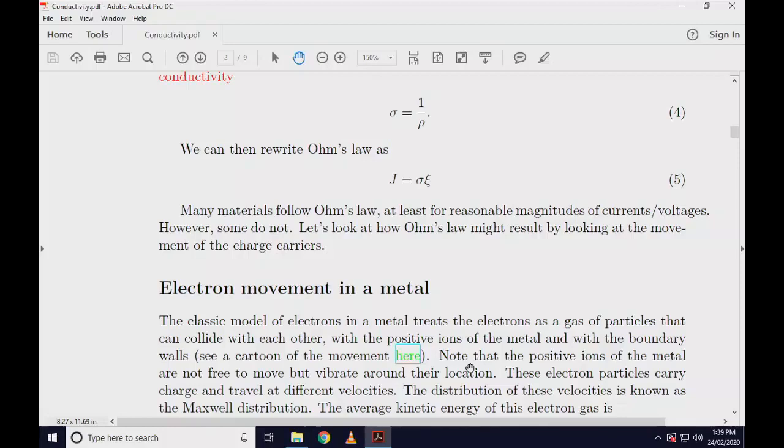But on average, that voltage is zero. Yeah? So on average it's zero. So this fact that there is a voltage, and you can measure it, if you get a chance, you get a resistor and put an oscilloscope probe across it, you will see these fine lines moving around zero. And that's the noise, what we call thermal noise, and that's because of this random movement of these electrons. So on average, there is no voltage.